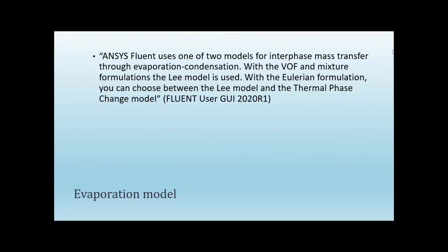ANSYS Fluent uses one of two models for interface mass transfer through evaporation condensation. With the VOF and mixture formulations, the Lee model is used. With the Eulerian formulation, you can choose between the Lee model and the thermal phase change model. In this video, I'm going to explain a case using the VOF formulation, so the Lee model is going to be used.